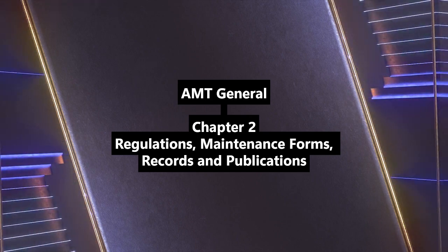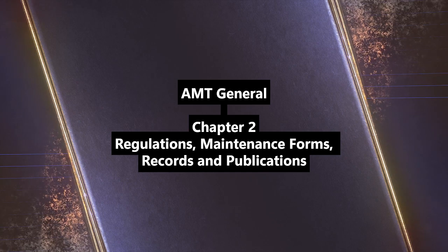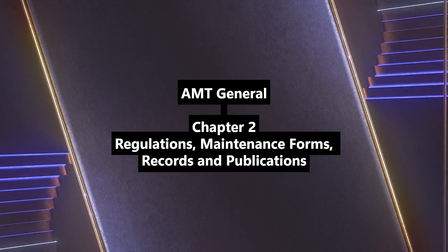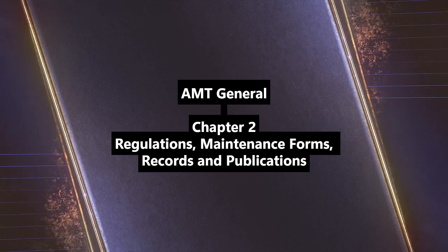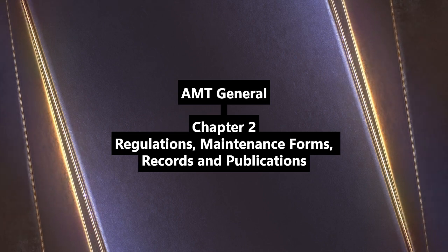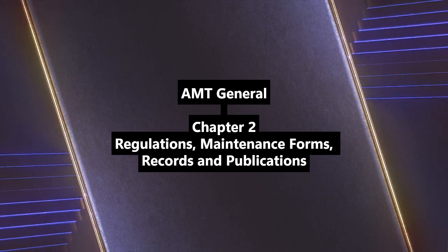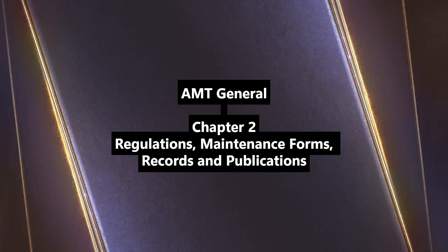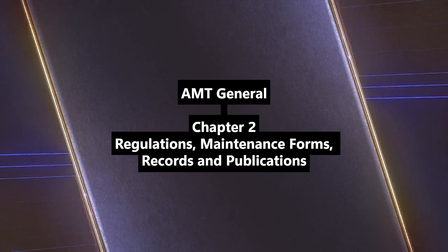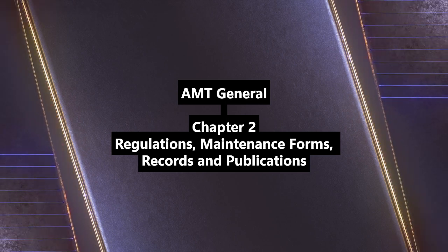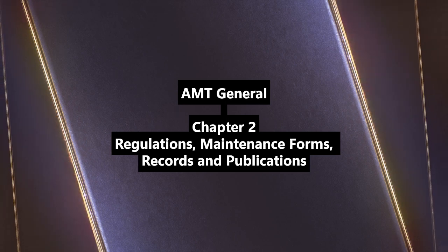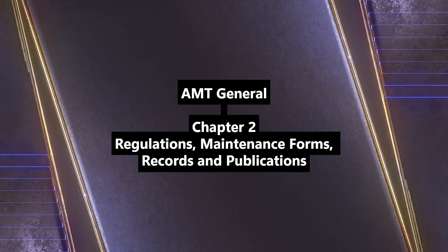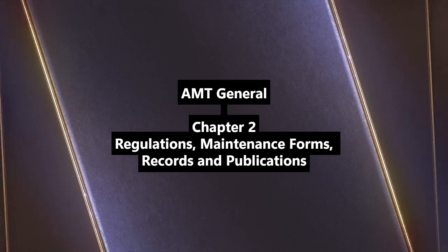Critical step. Always needs a maintenance record entry per 43.9 or 43.11, and maybe FAA Form 337 for major actions. Major actions. How do you know what's major versus minor? That's crucial. Before starting work, you need to know, what am I doing? Is it a repair, fixing something, or alteration, changing something? Is it major or minor? And major means? Affects weight, balance, strength, performance, flight characteristics significantly, and isn't done using basic accepted practices. Minor is everything else. Part 1 and Appendix A help clarify.